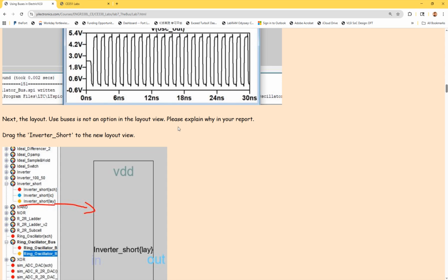Should we do that for layouts? So what are layouts? What these really are? Layouts are actually physical circuits, right? Schematics are symbols, but layouts are physical circuits. So you don't really want to create a bus and just one symbol to represent everything. It should be a physical circuit, right? So schematic is fine because these are just symbols. So for layout, if you have 11, you have to create 11 physical ones and make certain connections, right?